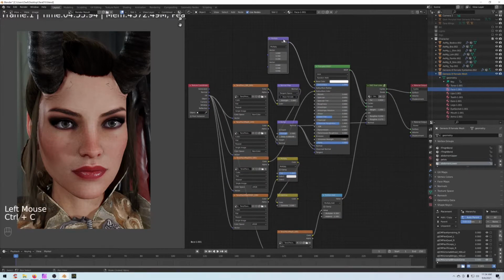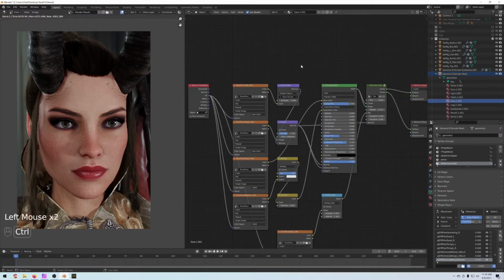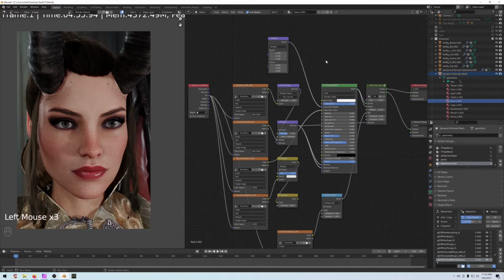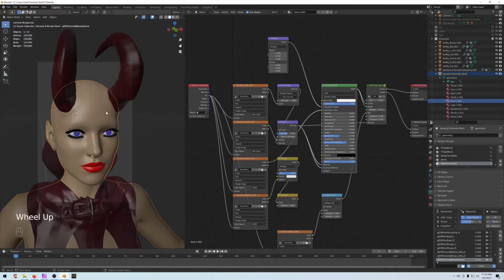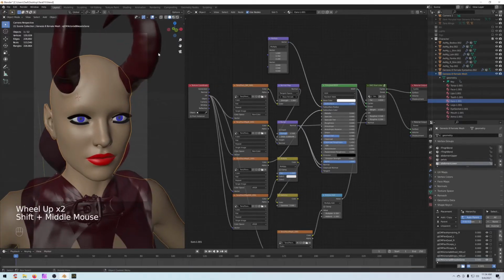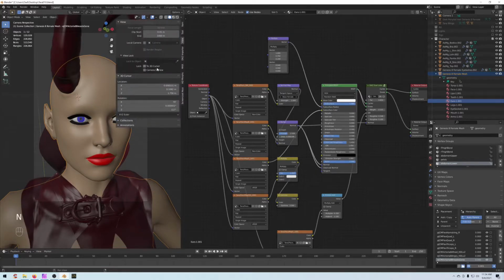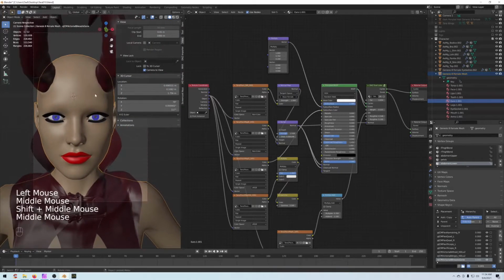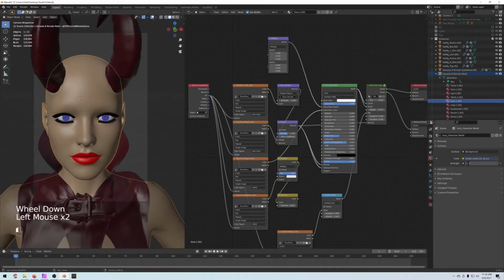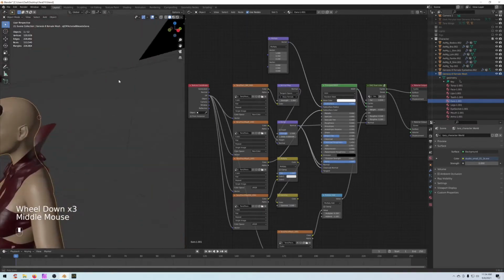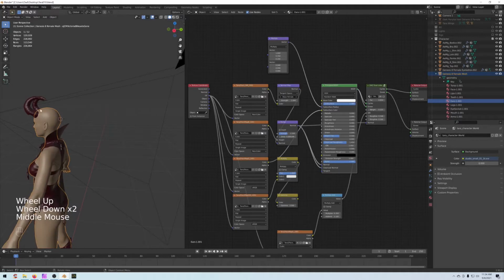We will Control+C copy in the ears, so Control+V paste, and put the diffuse right into the subsurface color, move subsurface up to 1, and let's do a test to see how well it comes through the ears with the backlight. So first thing I'll do is move the camera so we can see both ears, right about there, and we will turn off the world light, and we'll add a spotlight behind the character to shine through the ears.